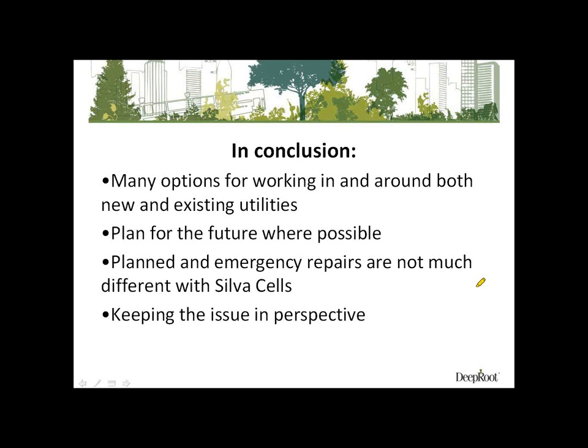But would a driveway count as a heavy traffic area? It depends what kind of a driveway. If it's for a bus turnaround where buses are constantly pulling in, dropping people off and picking them up, then I would say yes. Probably stay away from that, or we would look at doing some type of heavy pavement section over the top. But if it were a home? A home, absolutely, that would not be a problem.